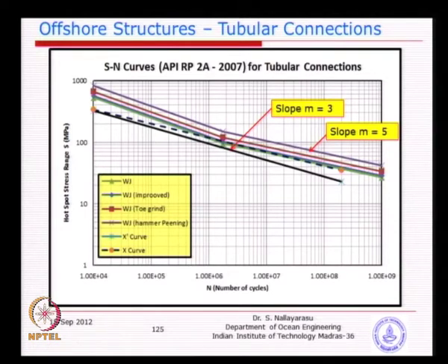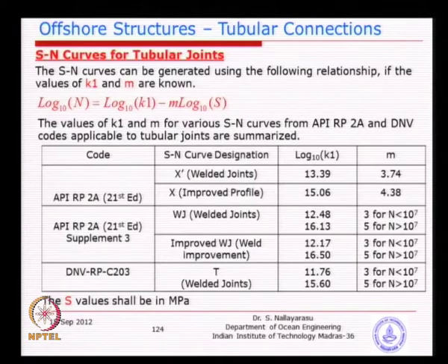Basically, to read it, or if you are given this type of numbers, the type of SN curve will be given, and a table will be given with all the SN curve K1 values or log K1 values, and you should be able to calculate using this equation.